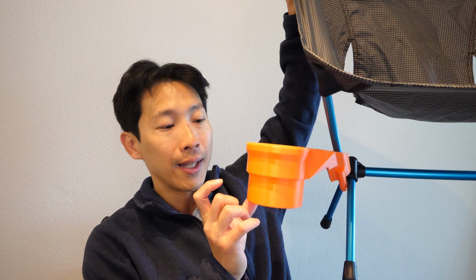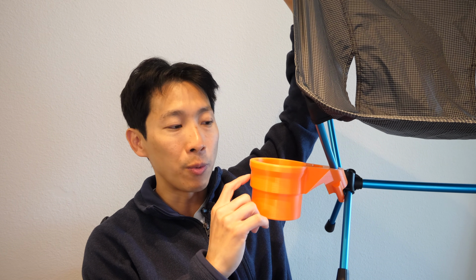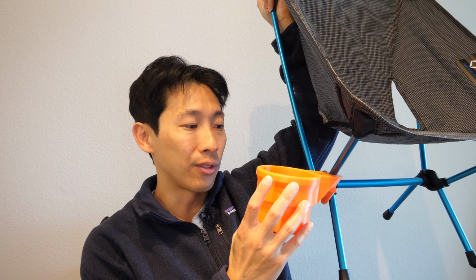I do have to warn that when you 3D print stuff, it's not actually food safe most of the time. So you want to print something that just holds stuff. It's a lot harder to print something that is load bearing because you need to make it strong enough. When you 3D print stuff, you also can choose how much fill each part has, right? Because you're not going to print this in absolute solid. It's not going to be 100% filled up with plastic, because if you do, it's going to cost a lot.